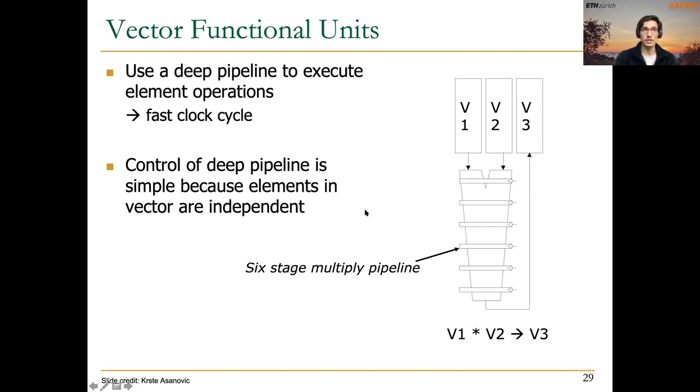What that means is that you can also execute the same instruction at the same time on another pipeline. So now we start combining the concept of a vector processor that only parallelizes in time with the concept of an array processor that also parallelizes in space. But we will see a more clear example very soon as well.